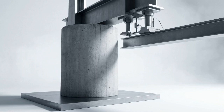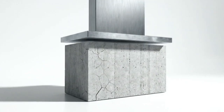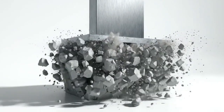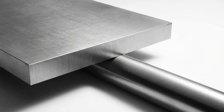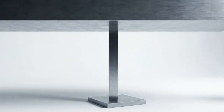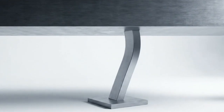When we picture structural failure, we usually imagine something being crushed. If you place a heavy concrete block under a hydraulic press and push hard enough, the sheer compressive force eventually shatters the material. Swap that block out for something tall and slender and apply that exact same downward pressure. The material never gets close to crushing. Instead, under a tiny fraction of the load that broke the concrete, the slender object suddenly and silently bows sideways.